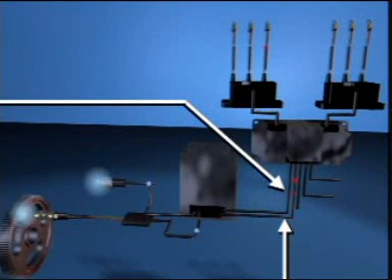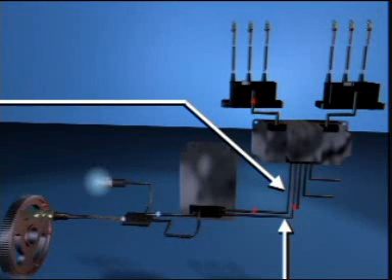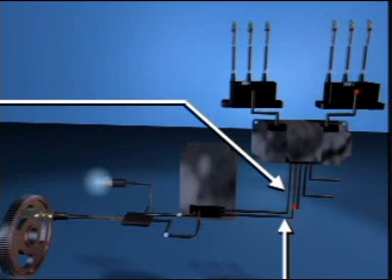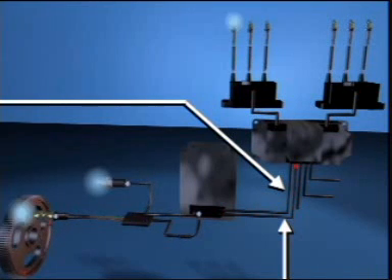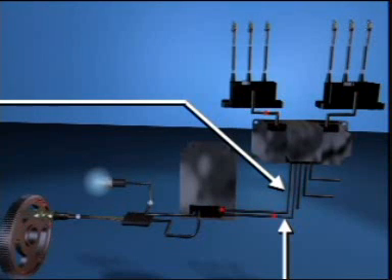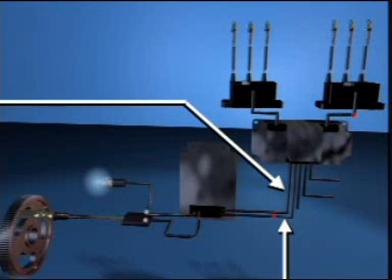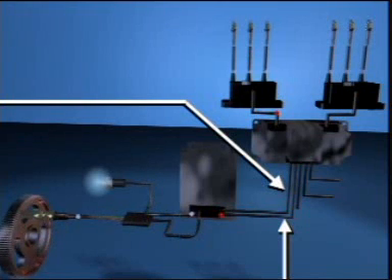The ECM uses the frequency of the signal resulting from the 6 evenly spaced cast protrusions passing the engine position sensor to calculate engine speed and, with the intake manifold pressure sensor input, adjust the ignition timing. The ECM recognizes the 7th signal from the 1 unevenly spaced protrusion as the indicator for the start of a new cycle. Each cycle begins with cylinder number 1 as the next cylinder to fire. The ECM uses this signal to generate the spark reference signal for the ICM.